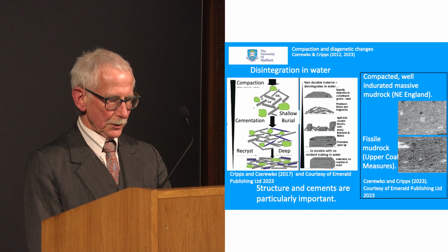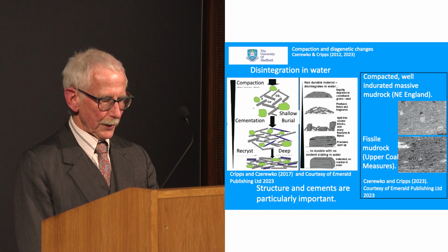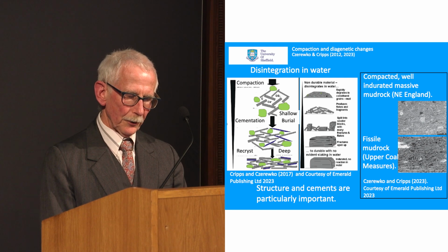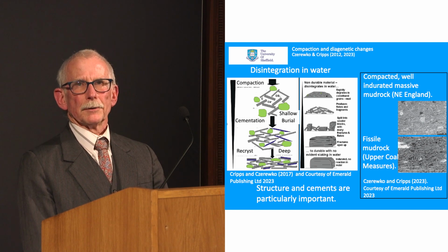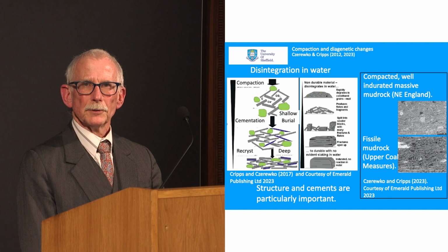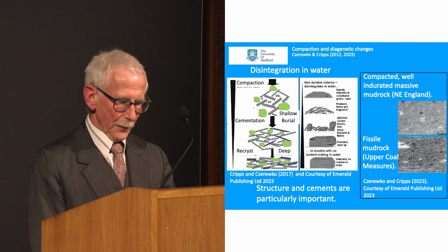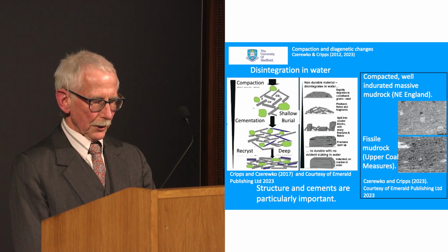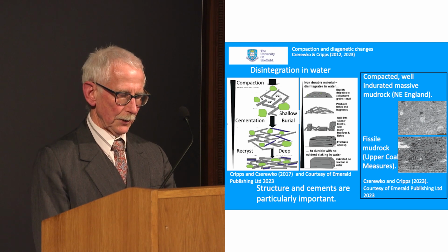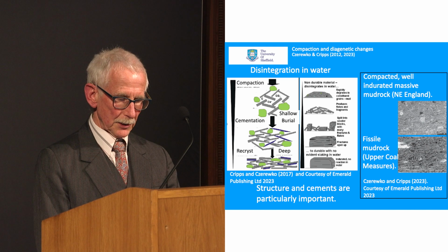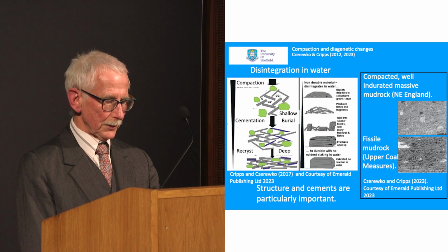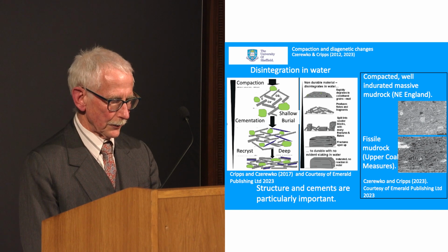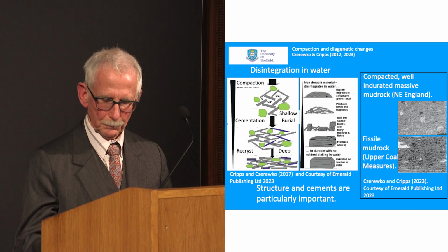The effects of the changes can be seen by the reaction of placing dried samples of the material in water, where a non-indurated compaction mud rock will degrade rapidly into individual particles, whereas the cemented types will disintegrate into flakes, chips, or chunks, depending on the cementation and the presence of weaknesses in the mass, which relate to the mineralogical and structural features that can be seen in the SEM images.